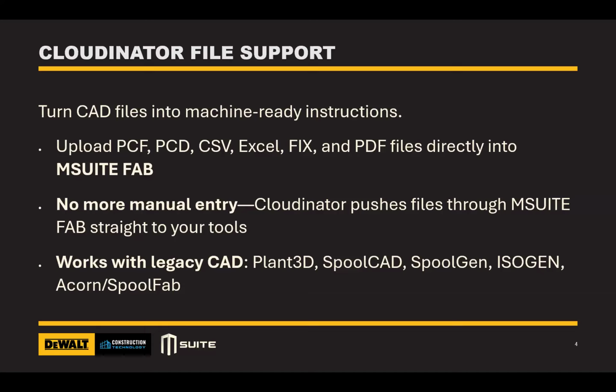After you've done multiple stages of tracking, everything you're used to doing in MSUITE, we can pull them down onto your straight cutters, like a Tiger Stop, Razor Gauge, Kentucky Gauge, or even a manual straight cutter, like just a bandsaw with a computer. We can pull them down using PypeServer Lite, which is a machine software that we sell for the shop, or we can pull them down into PypeServer Enterprise, which I'm sure most of you are familiar with, which does the multiple axis plasma cutting for complex and large diameter pipe.